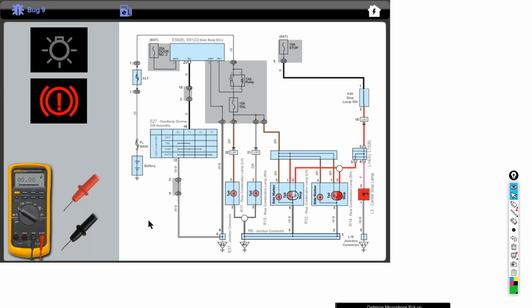What happens if we turn the stop lights and the park lights, tail lights on? Now the left side goes out, and all the others are working, so left side tail lamp and stop lamp are not working, side marker. As a technician, when I was working in a shop, I actually had worked on several cars with this exact problem. And a lot of times we call this sort of a feedback issue.